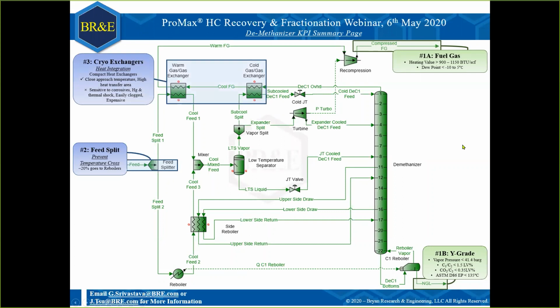Next, let's talk a bit about these exchangers. These aren't the typical shell and tubes, generally speaking. Most modern units use some form of a compact heat exchanger, which allows very close approach temperatures, up to like 3 degrees or even 2 degrees apart, to maximize the cooling. Because if you notice in this whole plant, no external refrigeration is required. It is all self-sustaining after it hits steady state.